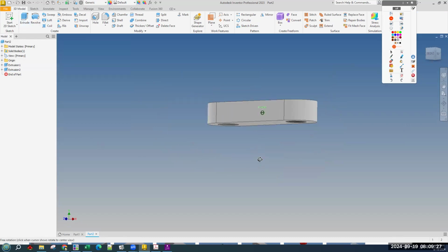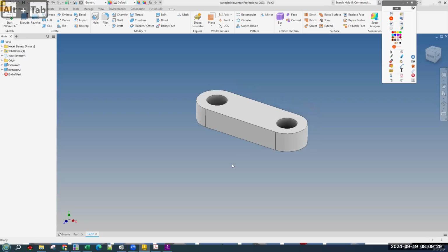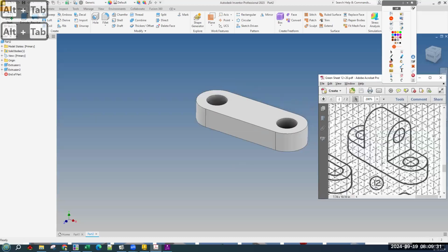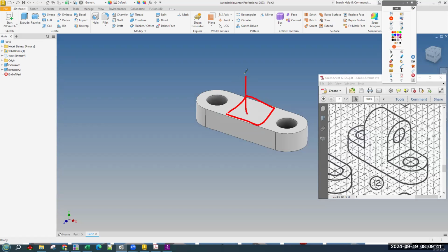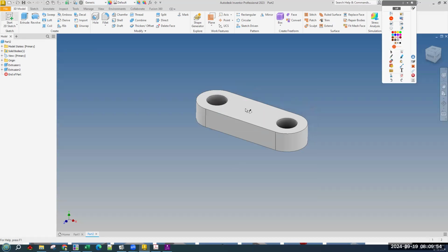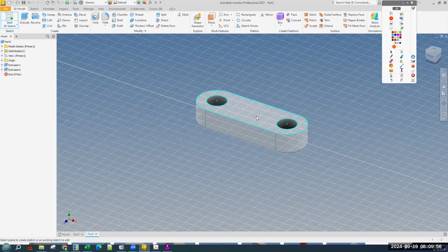Okay, and then the last portion, we're going to do very similarly to the other one. We're going to put a sketch on this surface. We're going to make our base, which is 4 inches wide, an entire distance front to back, and then extrude it up, and that will give us this sort of tower part that we can cut away what we don't want. So let's go ahead and sketch on here.